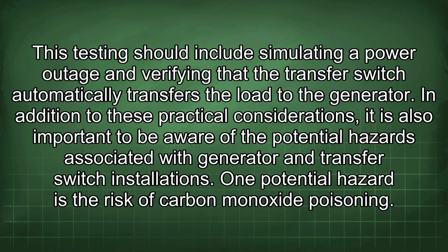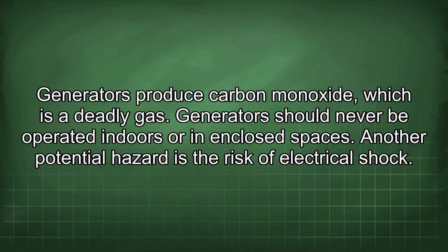the generator. In addition to these practical considerations, it is also important to be aware of the potential hazards associated with generator and transfer switch installations. One potential hazard is the risk of carbon monoxide poisoning. Generators produce carbon monoxide, which is a deadly gas. Generators should never be operated indoors or in enclosed spaces.